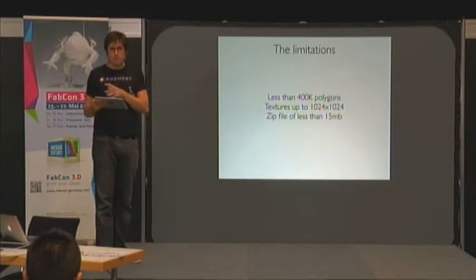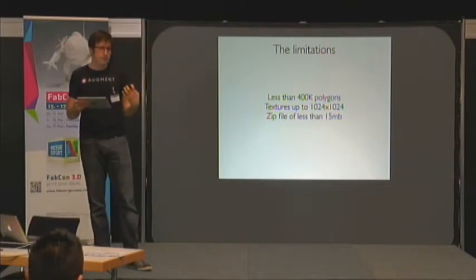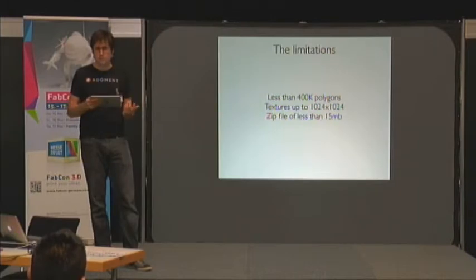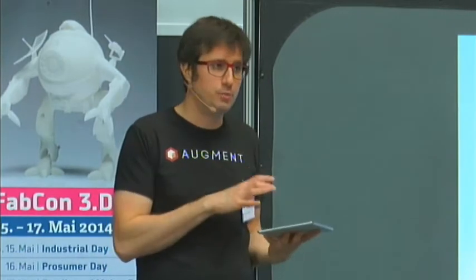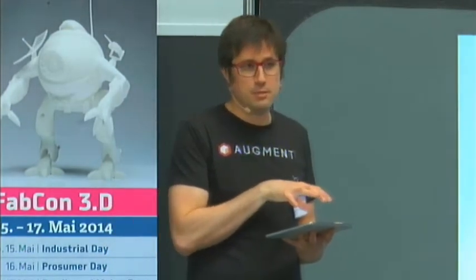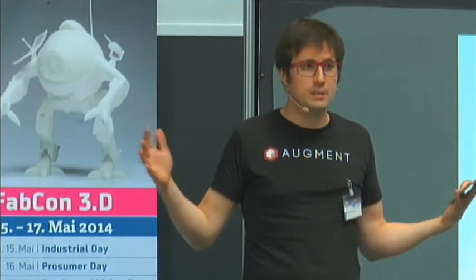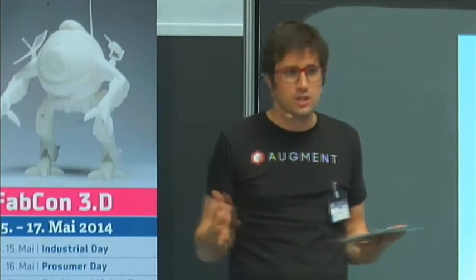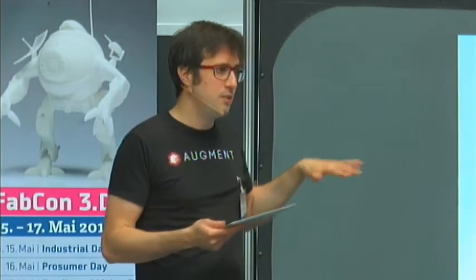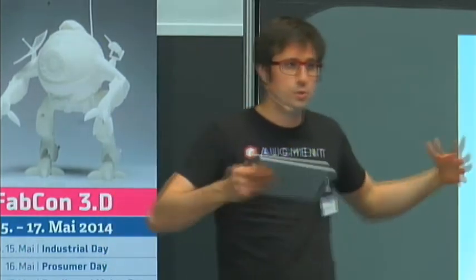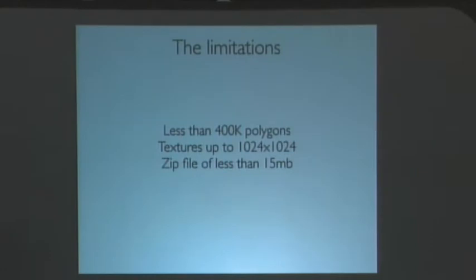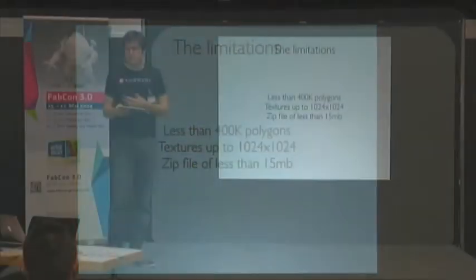There are some limitations that are inherent to the fact that we are working on a mobile device. As you know, and it's still the case, but maybe it won't be in the future, on a mobile device you have less memory, less power, and so you can't really put the biggest 3D models that you have. A million polygons won't work. So there are some hard limitations that we put in place for the app not to crash, because if you open a too big model, at some point iOS will just say, okay, you are taking too much space, and will kill your app without any warning.